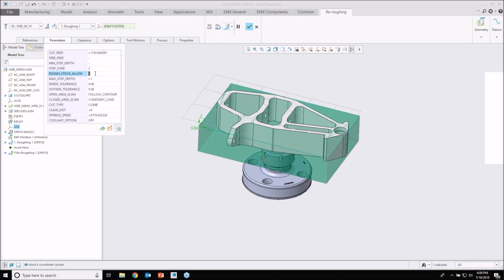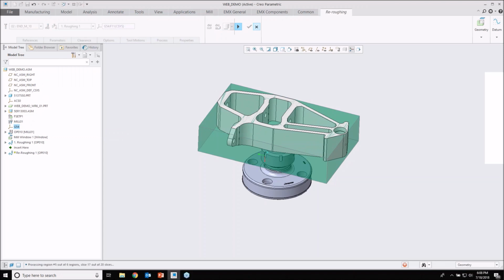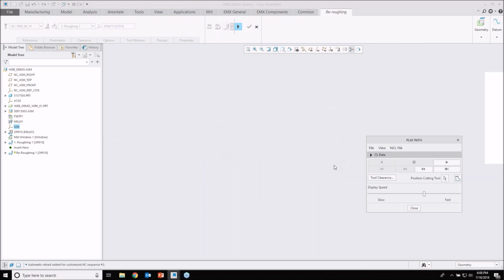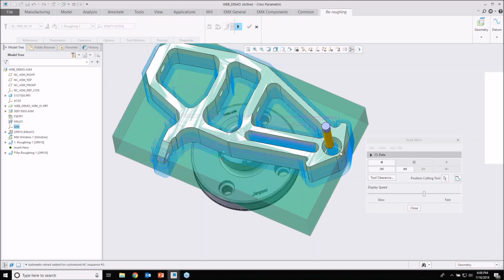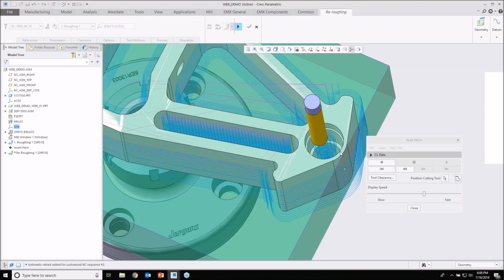Let's go to size on this, so it takes a little bit of material, and let's say 3mm deep. Okay, and let's see what that's going to give us. Okay, so it's cleaning up the surfaces, and it's going into a few pockets that we need to maybe do differently. So it's going in here. The 16 didn't go in there, and the 16 cutter also didn't go in this particular slot over there. So maybe take a different approach on that.